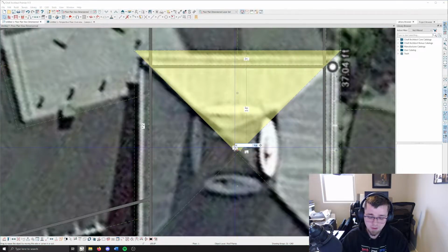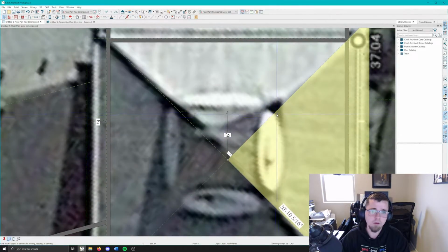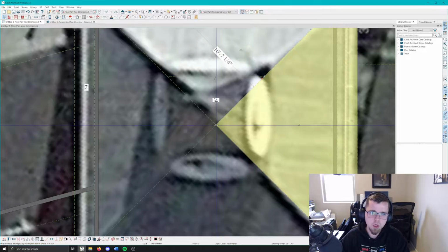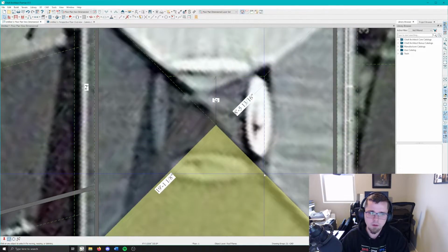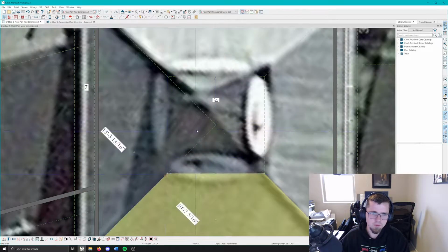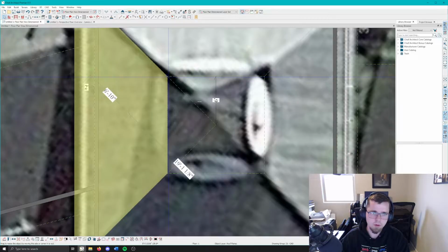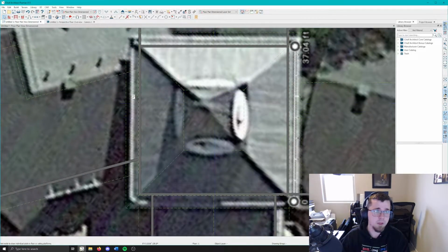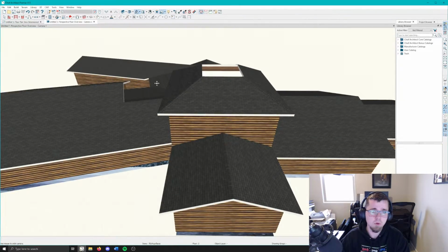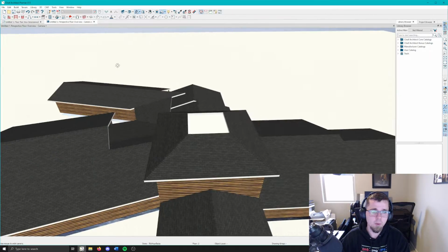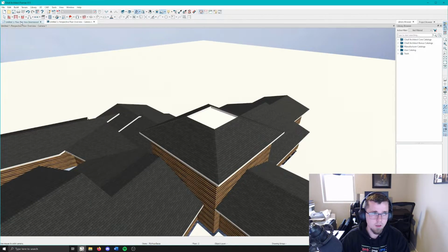The roof isn't going to line up, or the walls aren't going to be thick enough, or whatever it may be. Generally, it's a framing issue. It's just going to be real difficult to support everything, right? We're missing locations for the trusses to sit on. We're having to run in extra girder trusses, or it often becomes more expensive to build what they're trying to do because they decided to move a wall in 2 feet. And at that point, I say, hey, add the extra square footage. You're going to save thousands upon thousands, if not tens of thousands, on the framing alone to make that change.